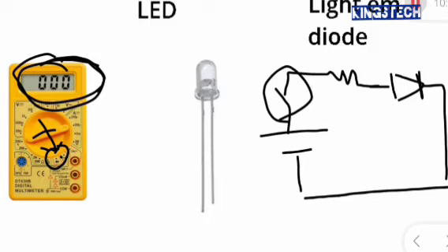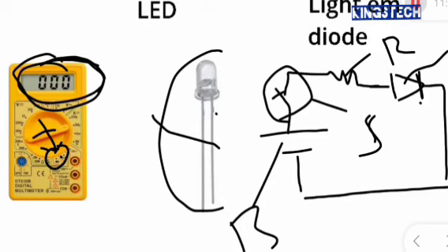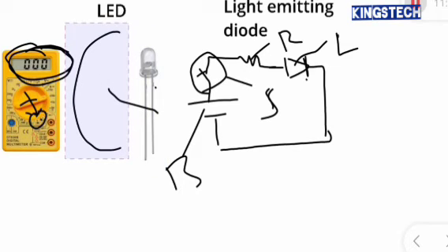So now in this simple circuit, this is the LED diode, this is the resistor, this is the switch, and this is the battery. If you close this switch, the light emitting diode should light up if it's good, if it's well polarized. I've showed you how you can know the polarities of the light emitting diode. So if it's well polarized, it should actually light up with this configuration I've showed you here on the screen, unless you didn't do it well.